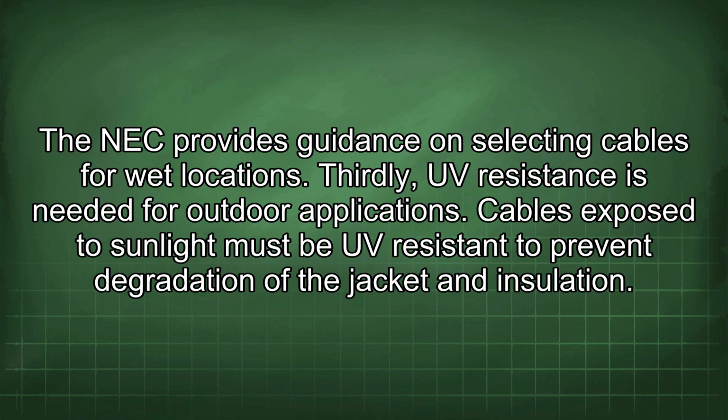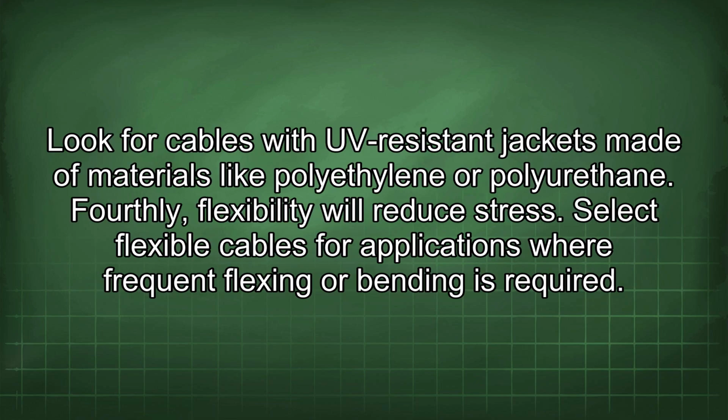Thirdly, UV resistance is needed for outdoor applications. Cables exposed to sunlight must be UV resistant to prevent degradation of the jacket and insulation. Look for cables with UV-resistant jackets made of materials like polyethylene or polyurethane.